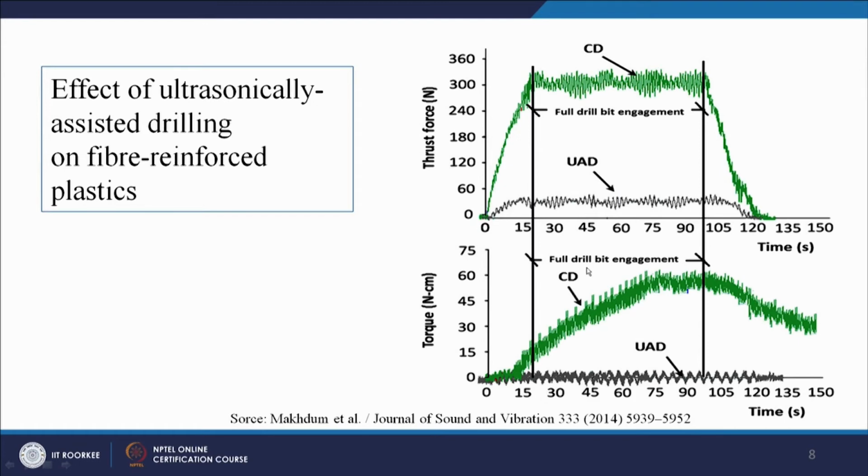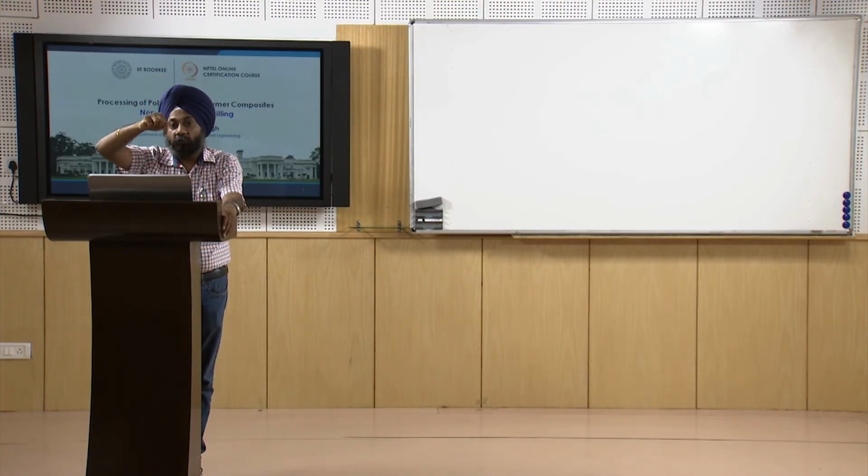If you remember, in previous sessions we have seen how the signal varies when the drill enters the composite laminate. Some of you who may have missed that session may also recall, or today I am again emphasizing, that these are the signals recorded using the dynamometer, which is used for recording of the forces, and a 4-component drill dynamometer is used for recording these forces.